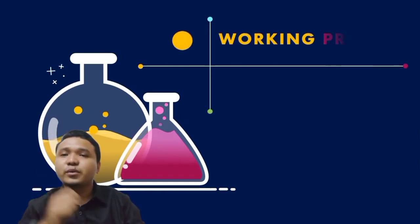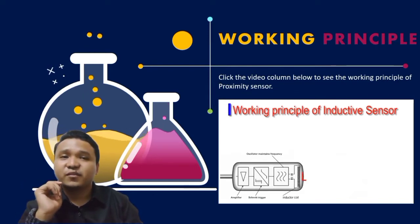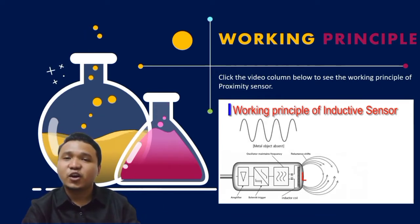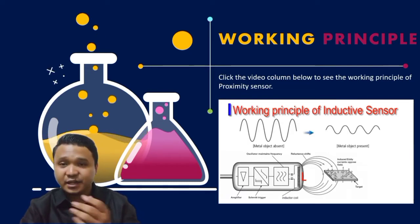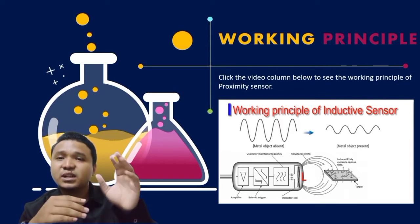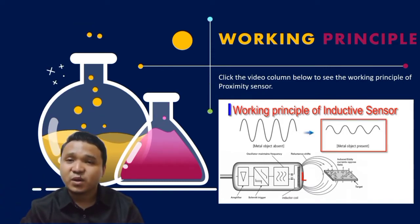So we go to the working principle of the proximity sensor. How does it actually work? If we look at the diagram of the inductive sensor, a high-frequency magnetic field is generated by the coil L in the oscillation circuit. When a target approaches the magnetic field, an induction current or eddy current flows in the target due to electromagnetic induction, which causes the load of the oscillation circuit to increase. Then the oscillation amplitude will reduce, or the oscillation will completely stop, or become zero.